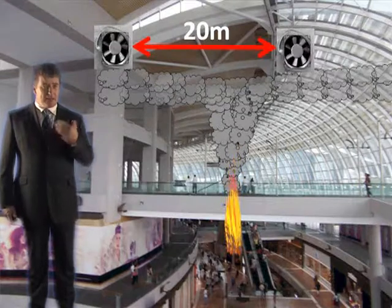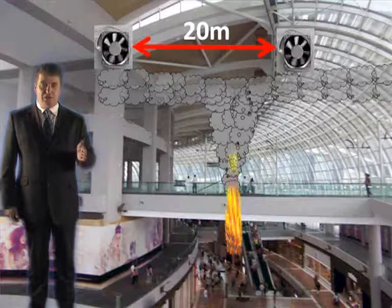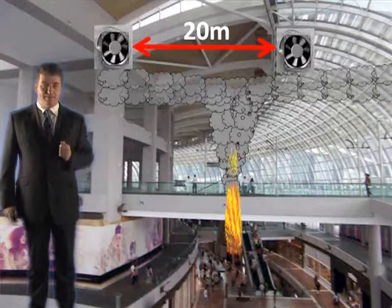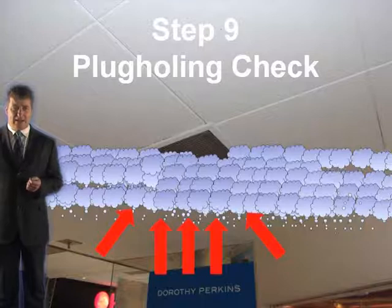Now remember, with mechanical ventilation, there is no requirement for stagnation checks. You don't have to do it with mechanical. So again, we can go straight on to step 9. Now step 9 is the plug holing check. Now this applies to both natural and mechanical ventilation.